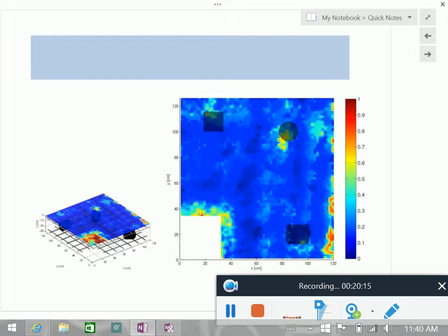Usually an area that can be tested by this method is like 1.2 meters by 1. You can test as large an area as you want. There are scanners where you can just mount the impact echo device or ultrasound or GPR on it, and then you define the spacing, and this is done automatically, so it just goes from one place to the other and collects the data.